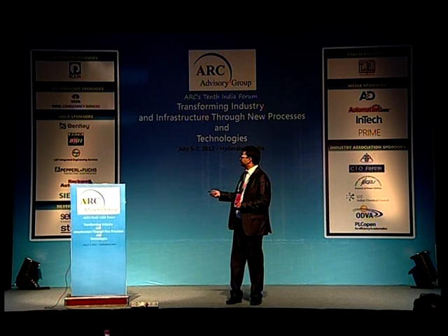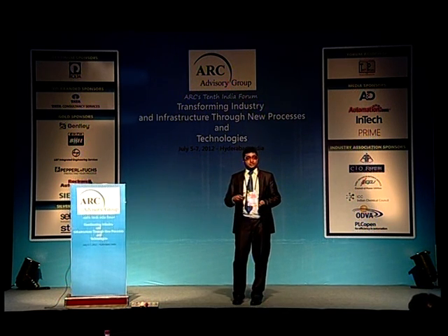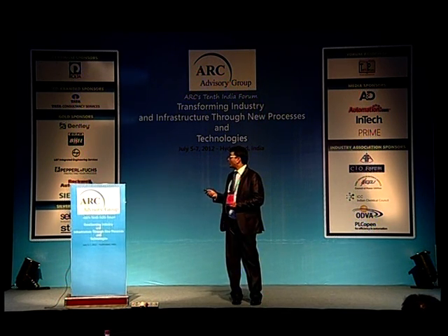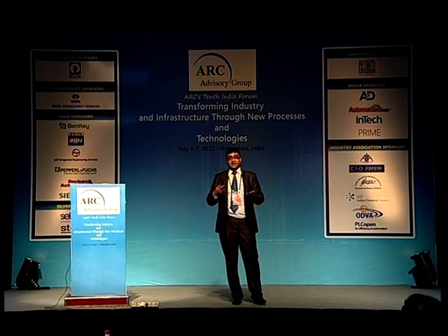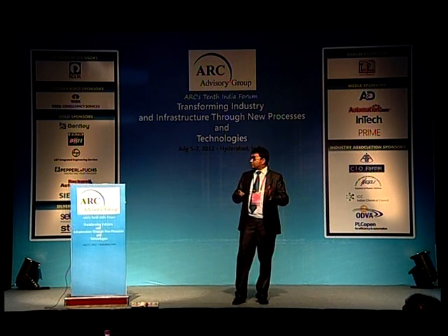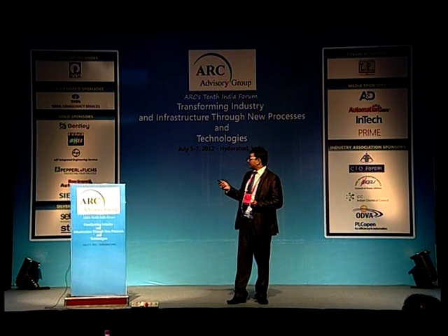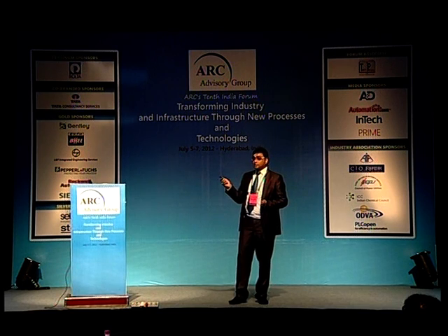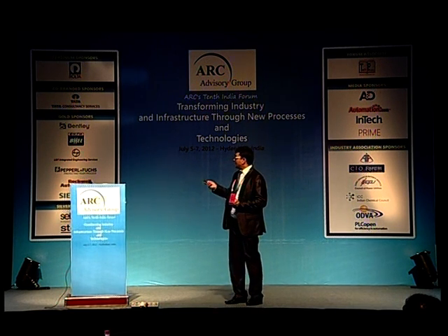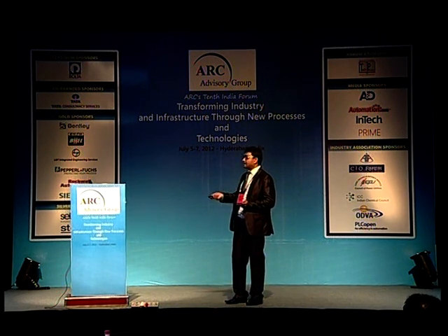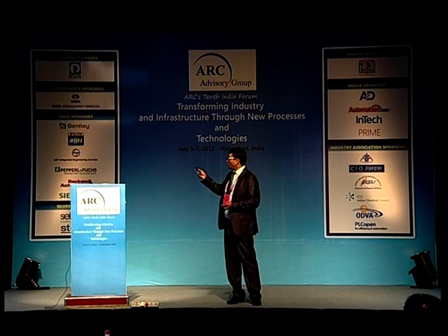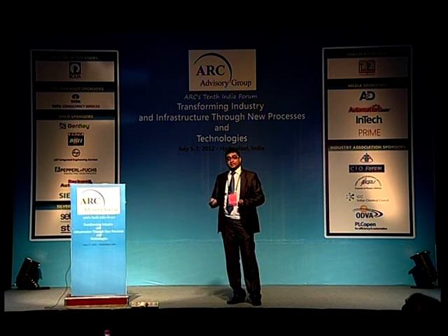Another optimization model which gives a lot of benefit as well is set point optimization, where the target is the improvement of the heat rate, which is about how to reduce the losses in terms of plant performance. So heat rate reduction is the objective of this module. If you see on the left side, all the actual values are displayed, and there is an optimal value which is generated by the system.